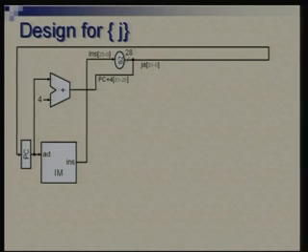Finally, for jump instruction, all that we need is putting the right bits together to form the destination address. Right? We don't need register file. This instruction doesn't look at register file, doesn't require ALU, doesn't require memory, and all that you require is some little circuitry to wire the bits forming the address appropriately.